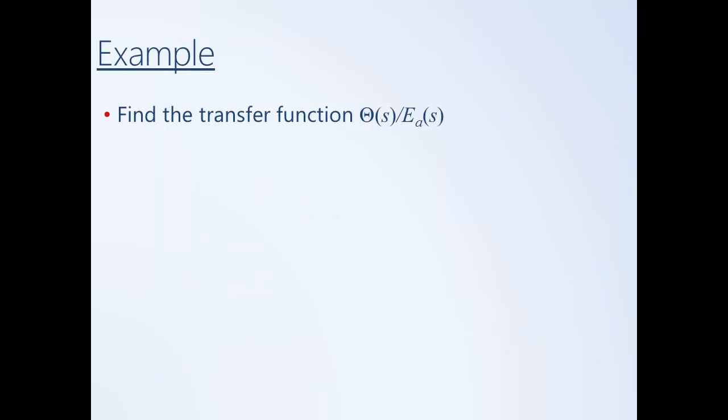So let's go ahead and try to find a transfer function for our motor. Those previous equations give us one dynamic mathematical model of the DC motor. An alternative type of model is the transfer function. In this case, I want to find the transfer function where the voltage applied to the armature is the input and the position of the motor is the output. You could imagine different situations where the inputs and outputs might be different. There could be a situation where we want to consider the speed of the motor as our output, or the torque of the motor as our output.